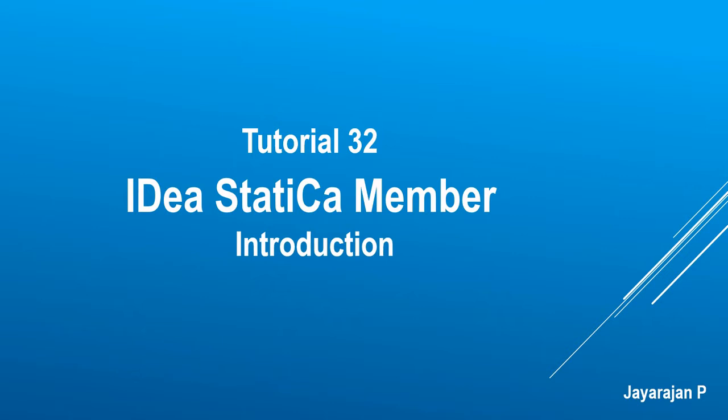So naturally, the first question would be, why Idea Statica member? The answer is simple. While Idea Statica member software performs the design and strength checks of steel structural members like any other tools available in the market, such as SAP 2000, ETABS, etc., it's also capable of performing additional verifications, namely the stability and buckling checks.